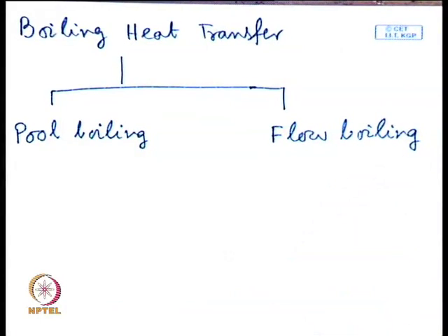So, pool boiling. Here the boiling takes place on the external surface when the object is submerged in a very large bulk of fluid which is in general motionless. That is what we call pool boiling. There are many examples of pool boiling. The most common example which we can cite,